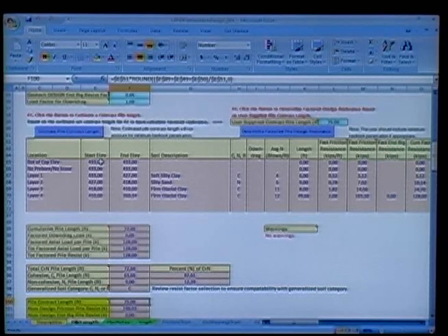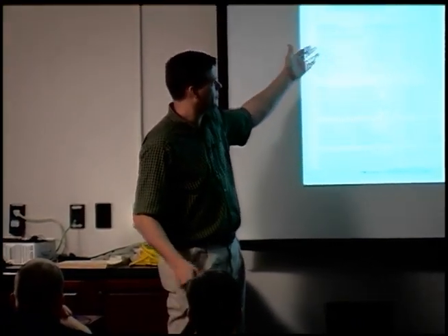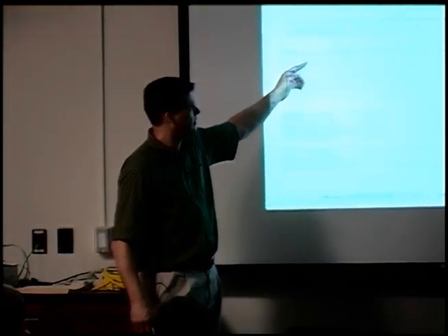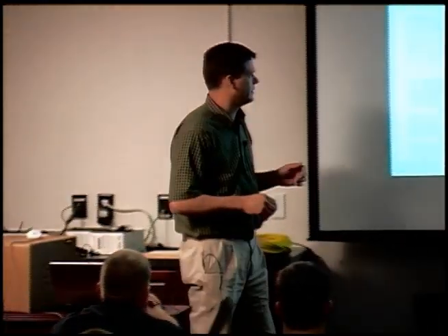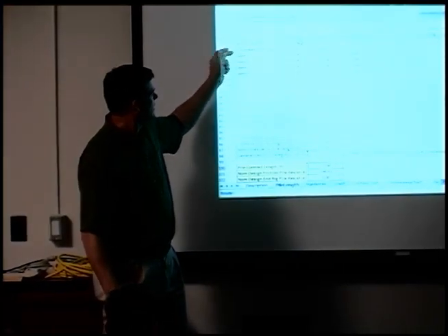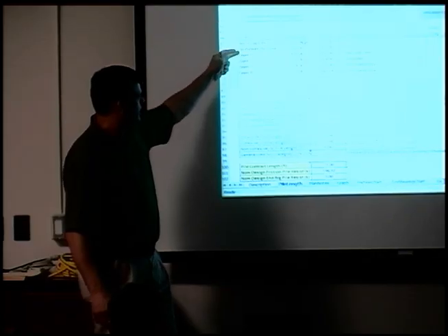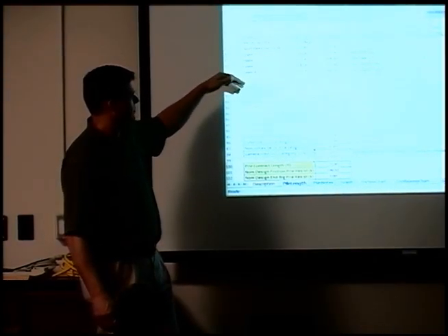And then what it'll do is go through, starting with the bottom of cap elevation, always on this line where you start, and of course there's no capacity there. It'll always put in this line. If you had pre-bore, it would show something to indicate that, and it would show the different elevations, or scour, because we don't want to count on the scourable material in the design because it's not going to be there to count on necessarily. So it'll show that as no resistance if there were any. And then it starts with the layers. Now if there were scour, maybe it would skip layers 1 and 2 and be down in 3, so it would skip over those if that was needed.